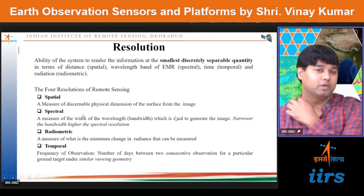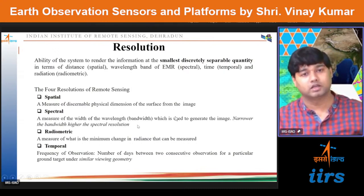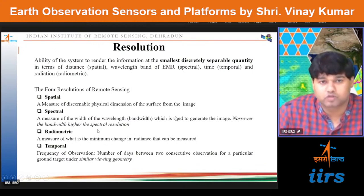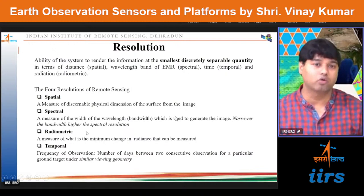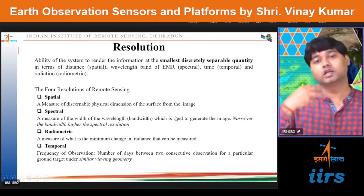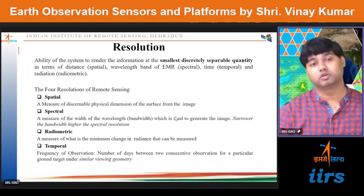Spectral is what? A measure of the width of the wavelength which is used to generate the image. Narrower the bandwidth, higher the spectral resolution. And radiometric is what? A measure of what is the minimum change in radiance that can be measured. I'll be telling you how it is going to be seen in the image. Temporal means what? How frequently we are revisiting the same area by viewing under the similar geometrical condition.